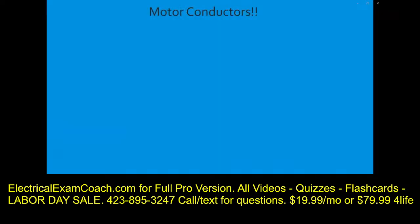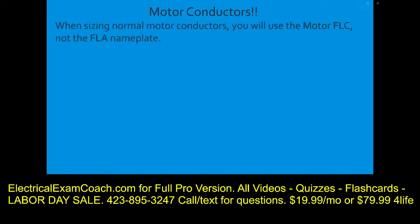Now we're going to learn about sizing motor conductors. 430 is one of the largest articles in the codebook, so I'm only going to show you what you're going to be testing on. When sizing normal motor conductors, you will use the motor FLC and not the FLA nameplate. FLC stands for full load current, and that's a value that we find inside the codebook. The FLA nameplate rating is typically the amperage value that they've stamped on the motor's nameplate.